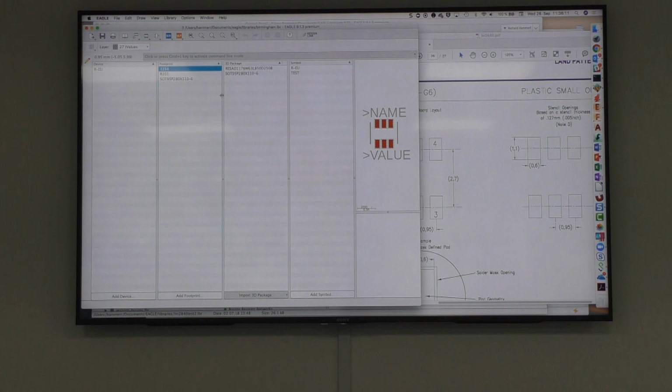If you think of manufacturing, all the components are delivered, but most of them are delivered on reels. And it could make sense to know how it's positioned on the reel. If I define it the same way in the library, that rotation 0 is the same as it is on the reel, then if you think about mounting machines, this would immediately match.